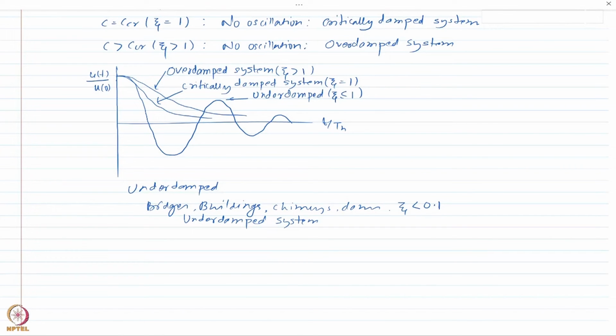So to make it safer for other people coming from behind you, or to bring it back slowly to its original position, that piston provides so much damping that the system works as an overdamped system, because we don't want it to vibrate back and forth.